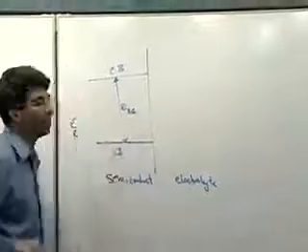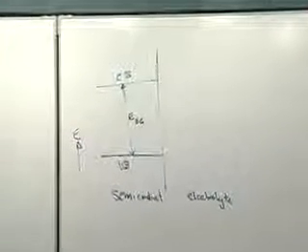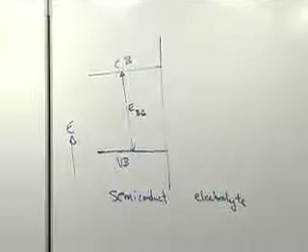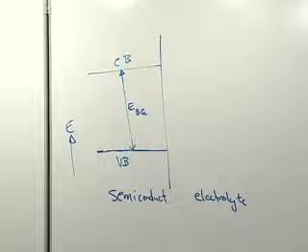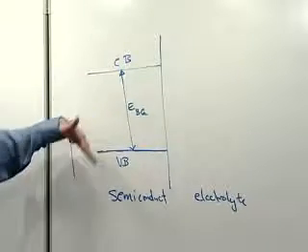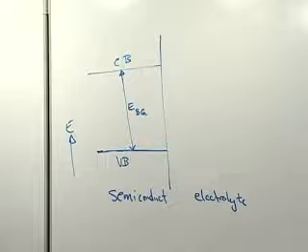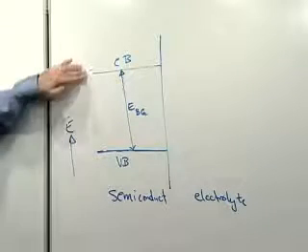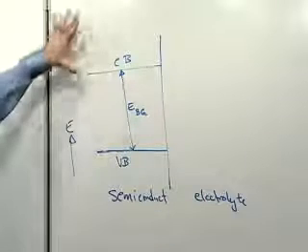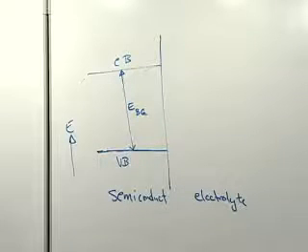And this is what gives your semiconductor its typical color. So silicon is black, right, because it's got a band gap of 1.1 electron volts, which corresponds to absorption of 1100 nanometers. That's in the near IR. It's black. It absorbs all the light greater in energy than the band gap energy, essentially. These bands, in other words, are very thick. There's lots of states in them.